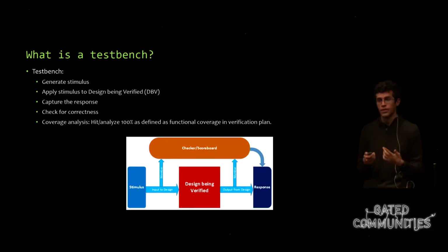Another important characteristic of test benches is that there's typically some way to measure coverage. And coverage is a very important metric that's used in at least hardware designs because it helps determine how far along your testing is and if you are actually hitting all of the code that you expect and all the branches you expect to execute. You absolutely do not want to go and fabricate a design that has untested code in it, and coverage is a great tool that's used to help prevent that.